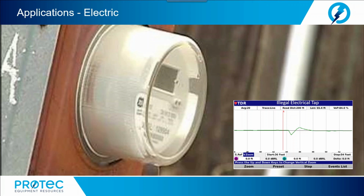In the United States and other similar networks, power is distributed using high voltage lines to the neighborhood. The high voltage is reduced by a step-down transformer near the customer's home. The smaller low voltage is 110 volts that runs most of our appliances. In most cases, homes receive two phases of 110 volts in order to power larger appliances that may run on 220 volts. These two phases are run with a neutral.